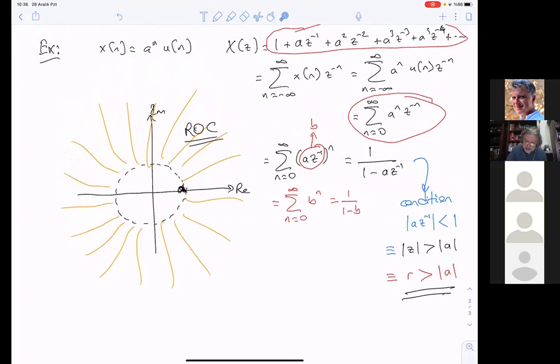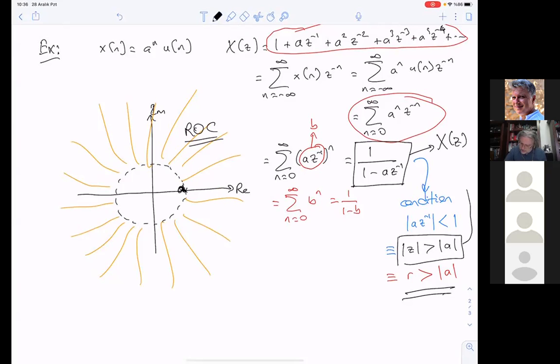And the Z transform is therefore this. This is X of z. And the region of convergence is this. So together, the expression of X of z and the region of convergence define the Z transform. The Z transform must always be accompanied by the region of convergence, just like the Laplace transform. We're not settled with just X of s; you have to also indicate the region of convergence. Remember that. Here it's the same. You have to tell me the region of convergence.